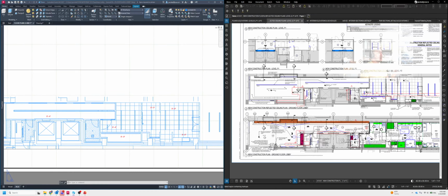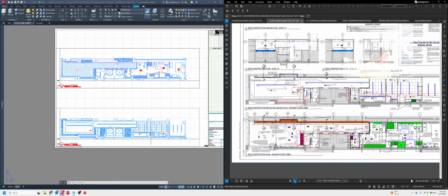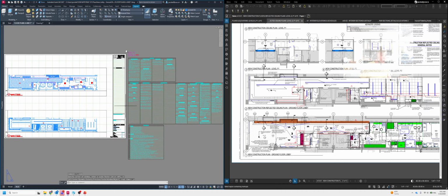The trim plan will have callouts like what we showed there. On top of that, it may refer to the finish schedule, which will have something like WB1 for wall base 1 or wood base 1. So you're going to want to look for that too. In this case, again, there's no trim on this project, so we're actually set to go here.